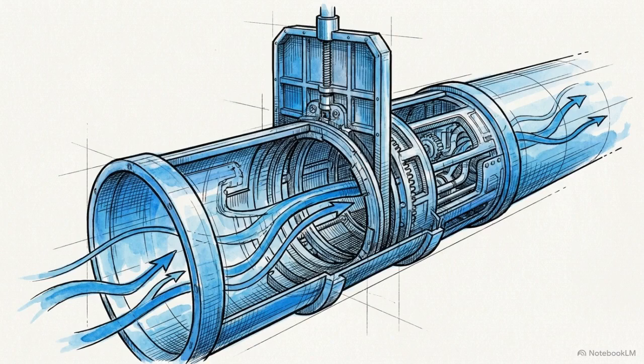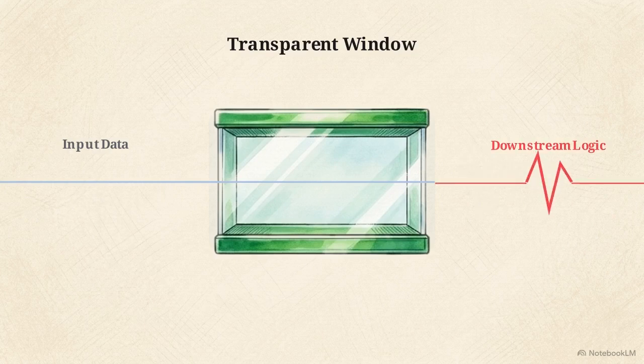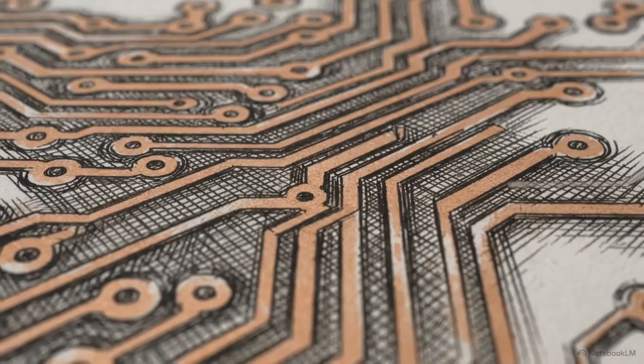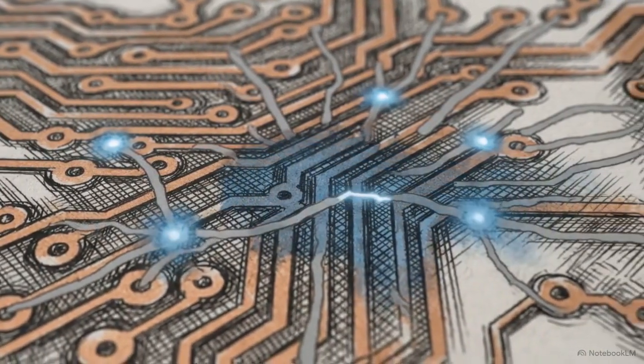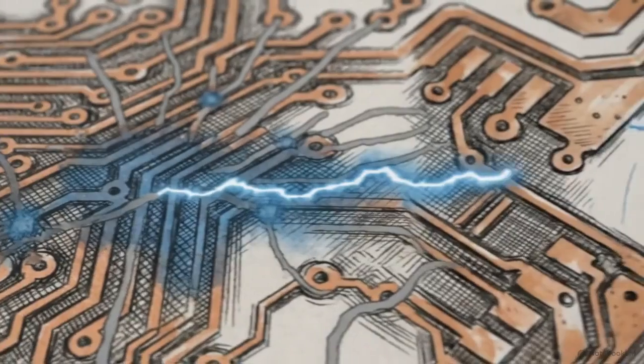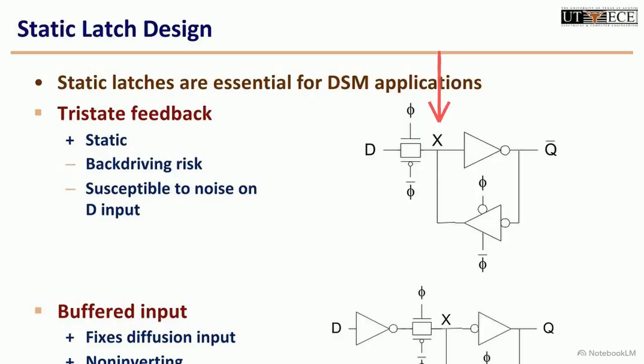While it successfully captures the state of the circuit, the D latch leaves the pipeline exposed. For a full half cycle, the barrier remains entirely open, leaving the downstream logic vulnerable to any noise or timing glitches propagating through the wire. Transitioning from theoretical timing to physical layout in deep submicron architectures introduces a stark reality. Managing state is entirely an exercise in managing noise.